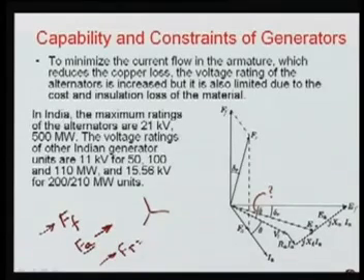Then we can add these two MMFs. Here you can see the value Ff minus Fa. Basically this is called the armature reaction. It tries to oppose, so your resultant MMF will be Fr equals Ff minus Fa. Here you can say this Fa is added. So this resultant will produce your resultant voltage. Now we can see that Ff will give your induced voltage, that is Ef, and we know this very well: this induced EMF Ef is produced by the field, and we have Er.